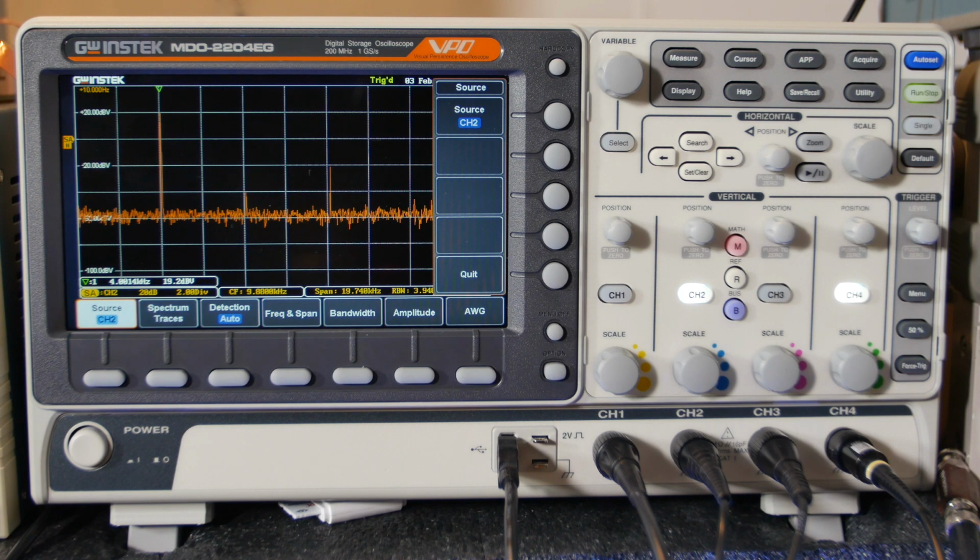Okay, now that's also a 20 dB signal. So let me drop the signal down to 0 dB. That's typically where these measurements are taken, and when you're looking at an amplifier catalog, they usually go at 0 dB, which, you know, is just a comparative place. Maybe they should be doing it at full power, right?